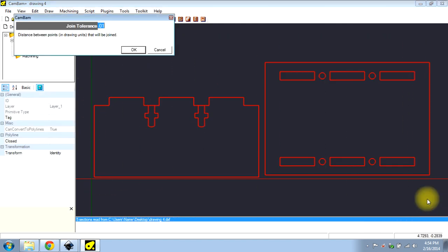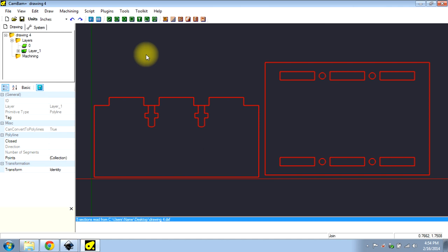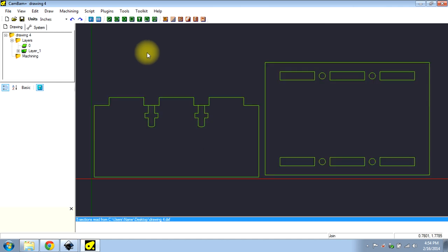And if this were going to a, first of all, controlled join, don't forget that. All those lines that I said get really close, they have to be at least a 100th of an inch close before this software will recognize them as connected. All right? Now, if I was going to run this on a CNC, I would not do layers in Inkscape.